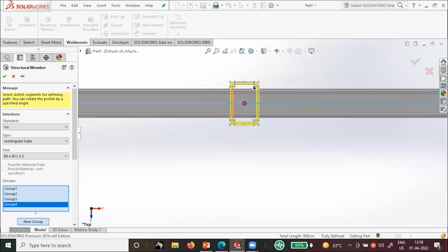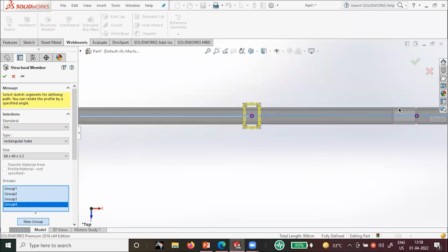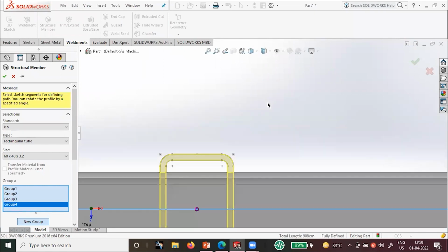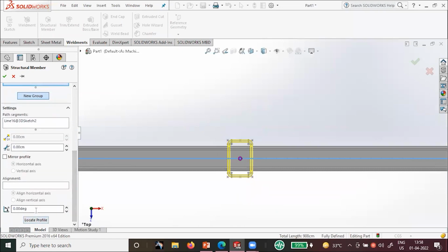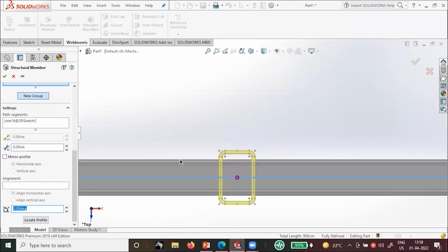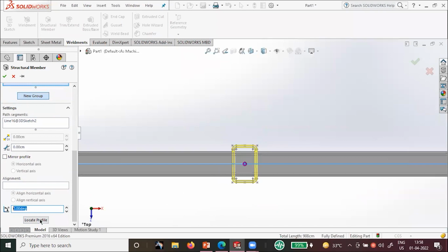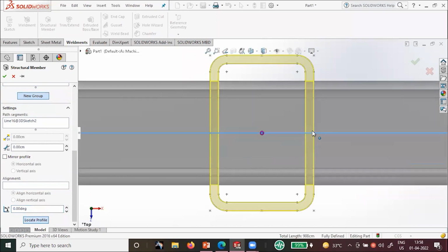So when I'm adding my sheet metal on this part, on this upper face, then this will be on the upper side. So we need to change the direction and length as per my requirement. So here I'm just changing my direction. This should be no issue. Then you can relocate the position as well. I'm just giving the first one, relocating the position to this point.